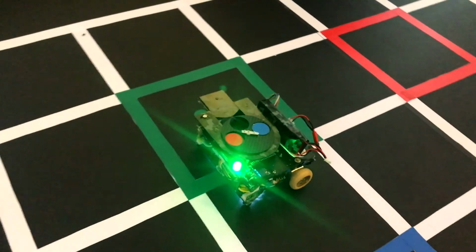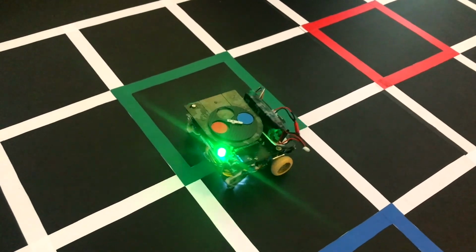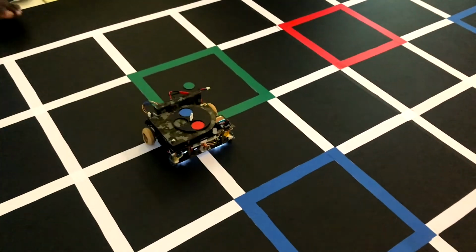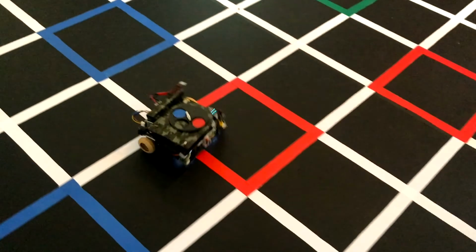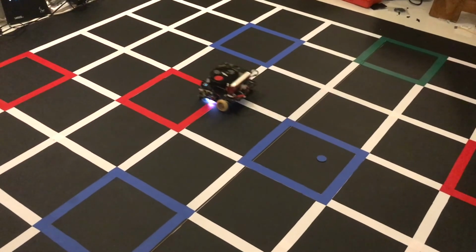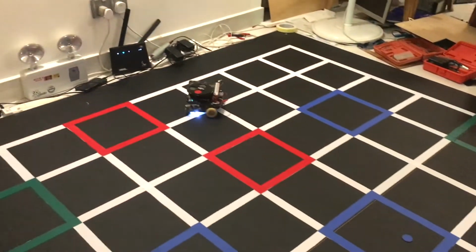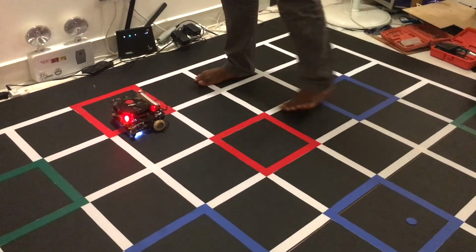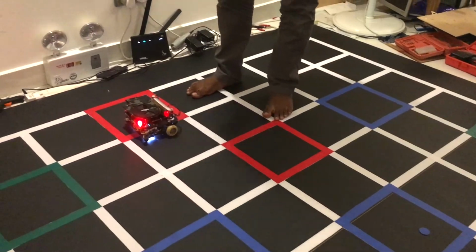The mechanism worked with two servo motors, one for selecting the required coin for the movement and another one for opening the door to drop the coin. Also, the best part was the rack and pinion mechanism we used to unload the coin.